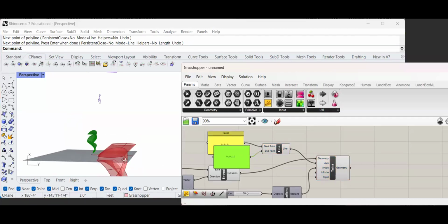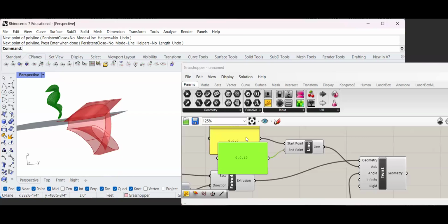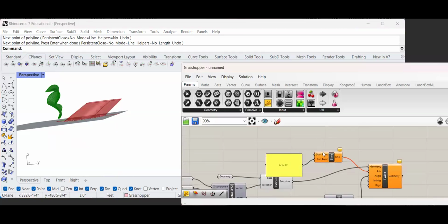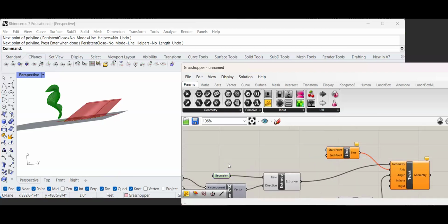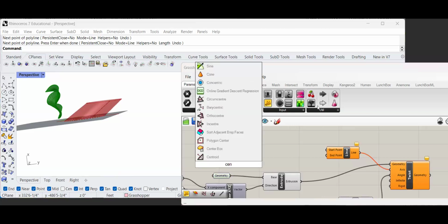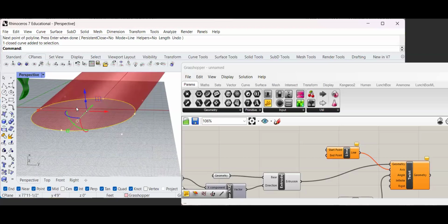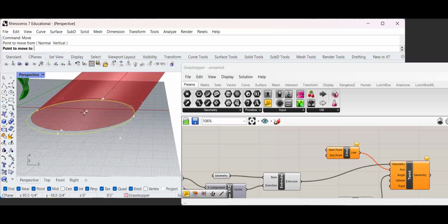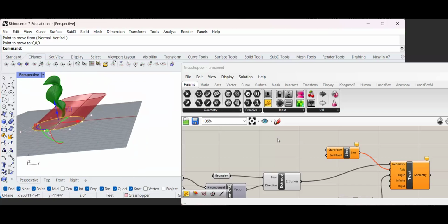Okay. Oh, wow. So a lot of trial and error. Actually, I don't like that it's 0, 0, 0. I might want to move that to my center point of the line. So geometry could be center, centroid from medians. Let's move this here. Move to 0, 0, 0. There we go. Perfect. Okay. Sorry. And then try that again.